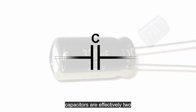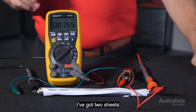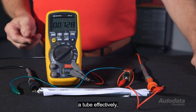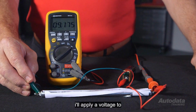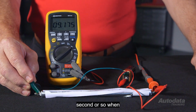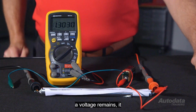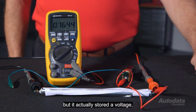Capacitors are effectively two pieces of metal separated by an insulator. They have the ability to store electricity and then release it again. I've got two sheets of aluminium foil separated by paper and wound up into a tube. Effectively, it's a capacitor. I'll apply a voltage to it. See there, I've got 9 volts. I'll just leave it there for a second or so. When I take the voltage off, you can see that a voltage remains. It won't be there for long, but it actually stored a voltage.